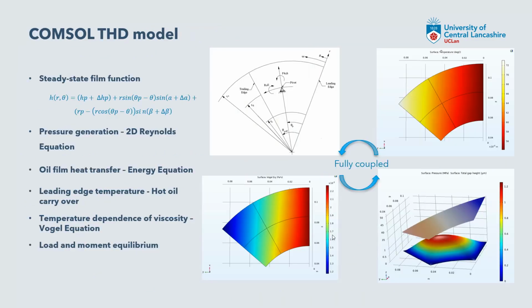And modeling, I developed a model earlier on in the project to look at controlling the oil film geometry specifically. This model is a thermohydrodynamic model developed in COMSOL Multiphysics, and it's just a steady-state condition, so there are no time dependencies of the oil film geometry. And with pivoted pads, you have